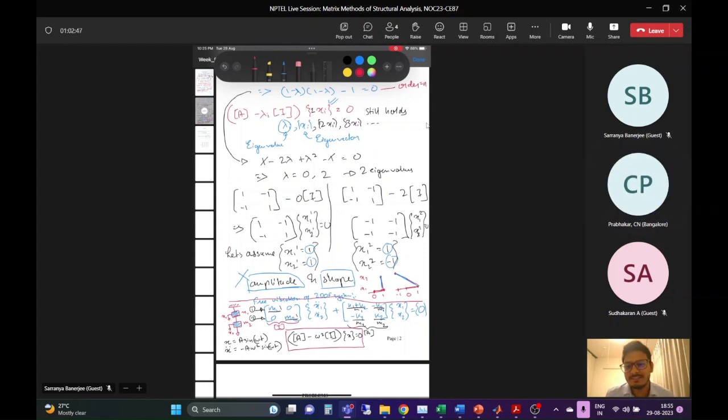So now this is an eigenvalue problem. Now we know this, right? So what are the eigenvalues and what are the eigenvectors? Eigenvalue is omega square, the square of the frequency. Anywhere you see eigenvalues, that is omega square. That is frequency, basically. And what are the eigenvectors? Those are the mode shapes, not displacements.